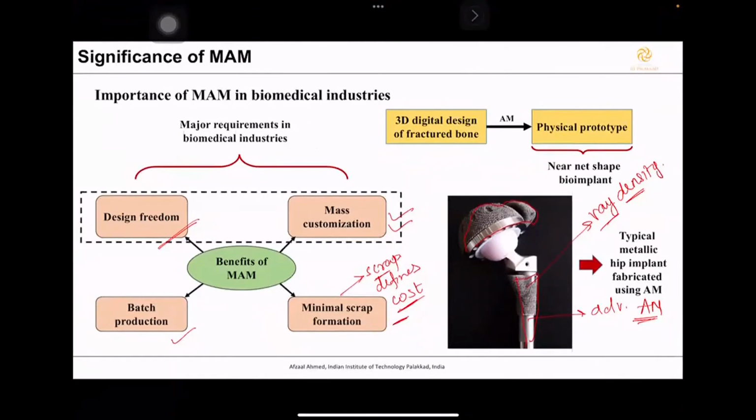If you talk about that, mostly for internal features, they use slurry-based abrasives. But there is a problem in that: you can't control the parameters. It's like a non-deterministic process. Whenever you want to stop the process, you can't stop immediately. That means the control is not there. Definitely there is no control.